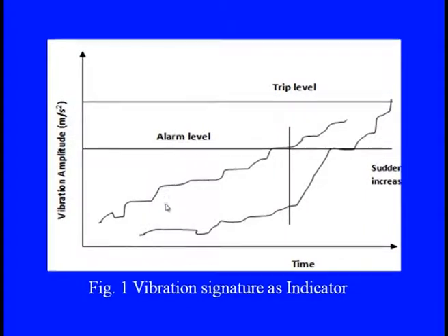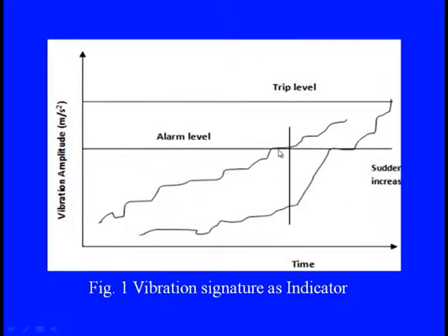Due to that, the vibration is continuously increasing. That means the exciting forces are quite dominating over the normal forces. So here we can set the alarming situation based on the transmission, and whether this vibration amplitude or energy at that point is now damaging other components. This is the alarming situation, and once it approaches that point, it can be tripped there. So the entire machine is now at shutdown.